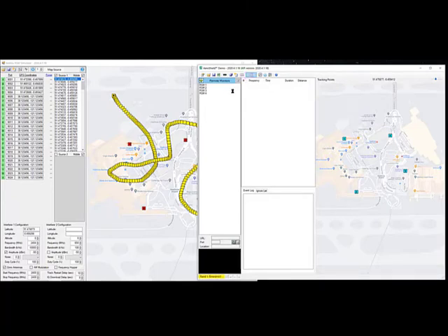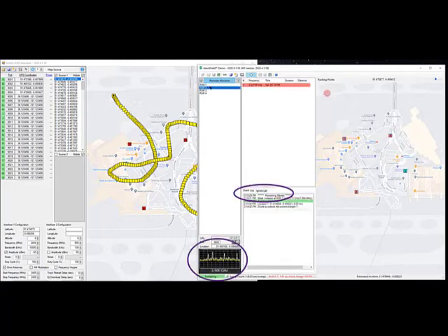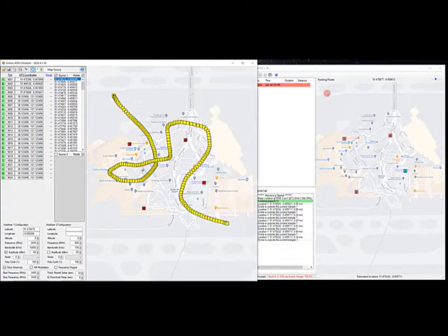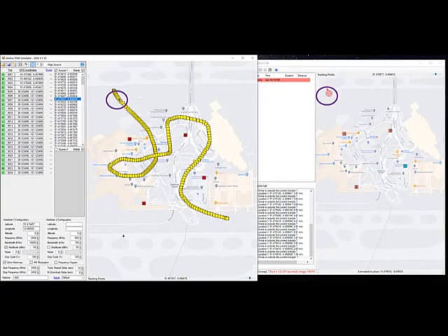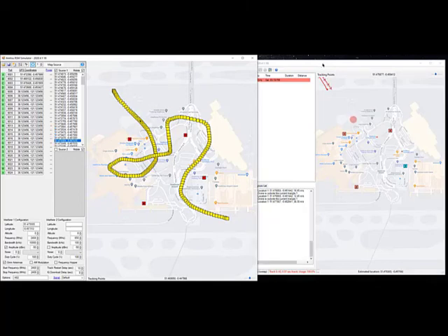Before the program begins, it'll cycle through each band of each probe, so 2.4 and 5.8 gigahertz, to set the mask, and then it automatically goes into monitoring mode. We set the simulator to begin, and you can see with each track here, we're still kind of far away from our network position, so we won't get that accurate until basically the drone comes in fairly close, within that radius that we examined with our coverage map. So you can see we're starting to get a good track with that bullseye coming into the network.